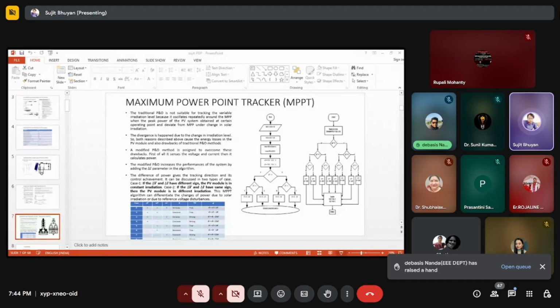Before going to the microgrid system, I have given some idea about how the grid integration works. Grid integration is the most vital thing. You will design the microgrid system, but how will the grid connectivity be there? How can you connect to the grid? This is the most vital thing. The microgrid system has variable frequency, because solar and wind have variable frequency, and the grid has a stable frequency of 50 Hz. So how will we connect this microgrid to the grid?